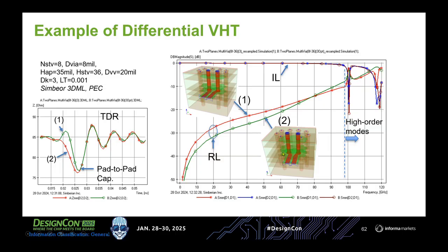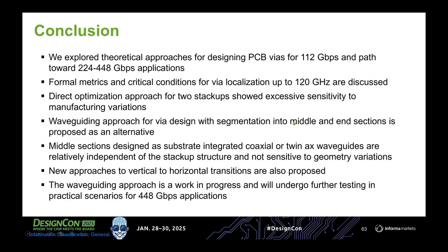So then you don't have many options, not many variables to play with. Right here, you just create a 100-ohm transmission line, and then you have only the pad diameter and the size of the trace that gets into this pad. So you can reduce it or increase it and play with this and see. It usually works at low frequencies, and then you get into this model transition area. So